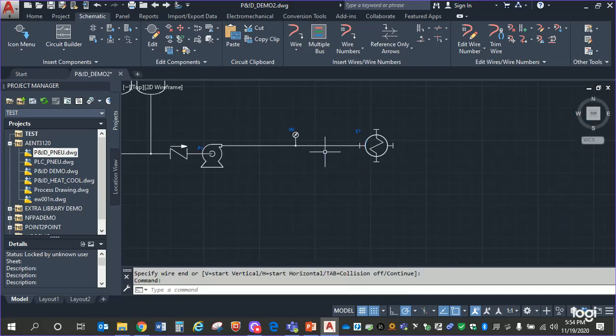Now, what's the difference between a sensor and a gauge? Just one reads out, right? Yeah. A gauge senses something, right? Temperature, pressure, humidity, flow. So does a sensor, but a gauge is really doing it for the purpose of us to read it. It's human readable, versus a sensor, which typically is not. Meaning I can't look at a heat sensor and tell you what the temperature is. Old school human machine interface. Mm-hmm. Old school HMI, I like that.